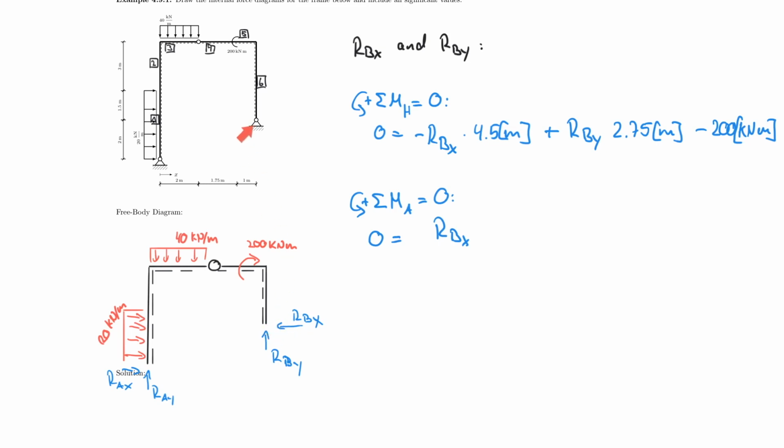It's acting here and it's turning about this hinge. So effectively it's turning this way around, which makes it counterclockwise, so that makes it positive, but I also have to find that distance from here to here in a vertical manner. That would be a distance of 2 meters. So 2 meters, and now it's turning counterclockwise, as I said, so that's positive.